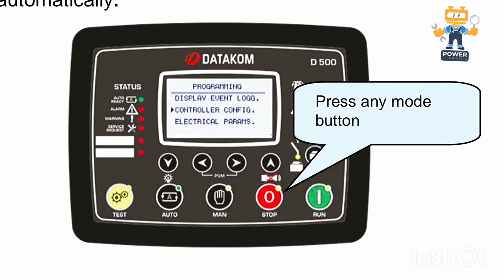So in today's video we will discuss about Datacom Genset controller D500. As you see in front of your screen, this is the front side of the module and I will show you the practical wiring which is behind the controller, not the drawing today. For the technicians who don't know how to read diagrams, we will show them terminal wise what the terminals are, what wire you need to connect and what the symbols are.